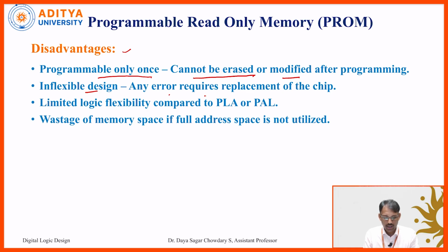And limited logic flexibility compared to PLA or PAL. In previous classes we discussed the PAL and PLA concepts. When compared to those, this has limited logic flexibility. And wastage of memory space if the full address space is not utilized, because these PROMs are fixed with address memories. So we already used that 6 into 64. If we don't use all these inputs and outputs, again there is a wastage of memory in this particular PROM.